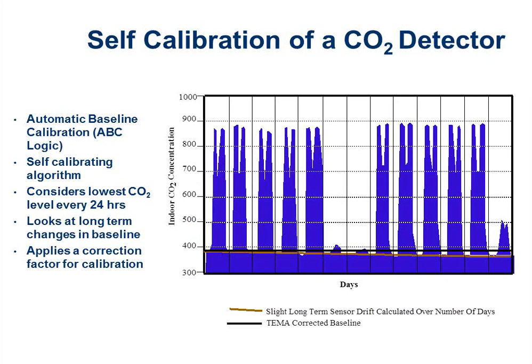So what it does in those 4 hours is enough time for air to leak in and out of the building envelope naturally, for these sensors to stabilize themselves to a CO2 level that's matching what's outside, and the outside air levels are very consistent throughout the day, night, and year. So they basically calibrate themselves to the leakage of the outside air, if you want to think of it that way.